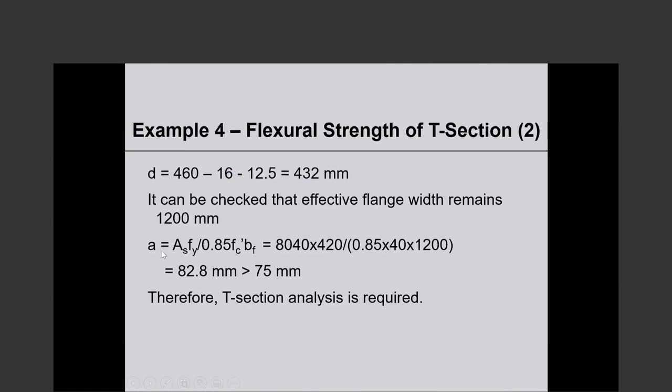Well, we are checking whether the stress block depth is larger than the flange thickness.